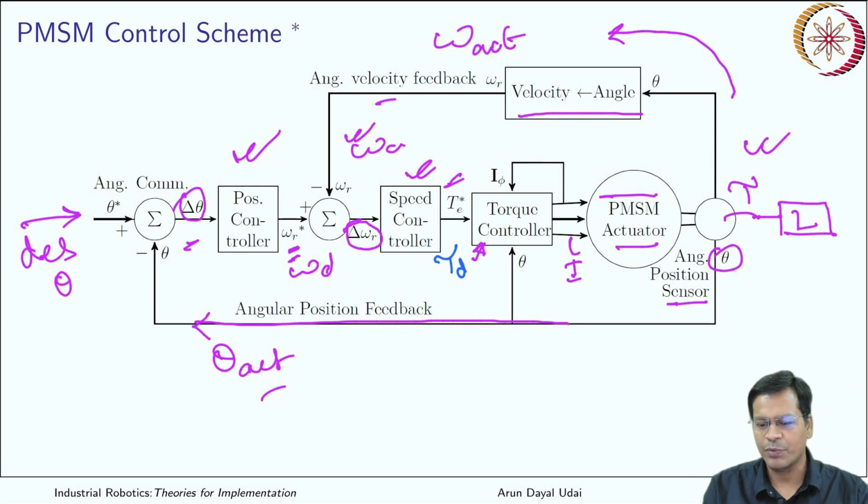That model, by measuring the current in its coil, is able to estimate the actual torque. So this is the desired torque, this is the actual torque. The difference is used by this torque controller. Ultimately it gives you an output which is current. So current is finally fed to this.